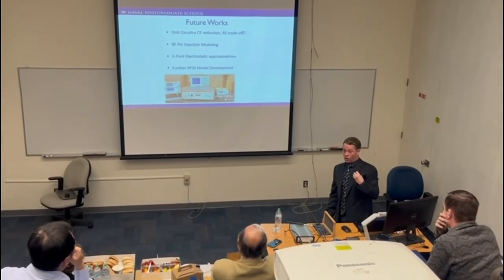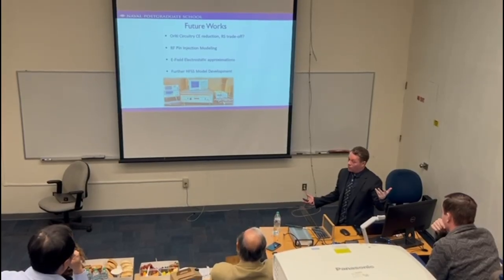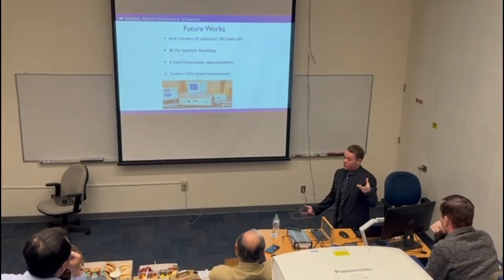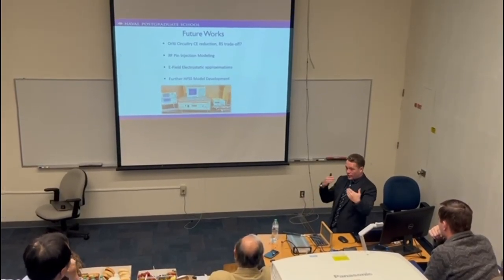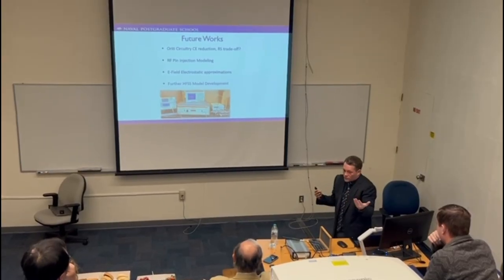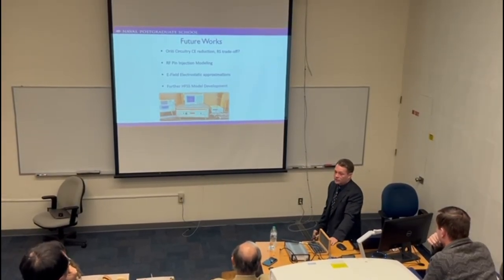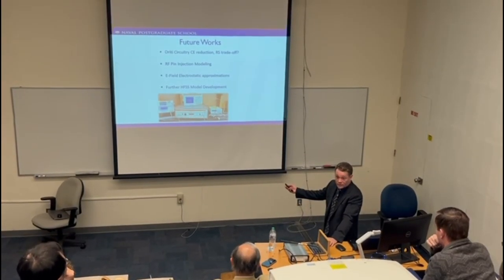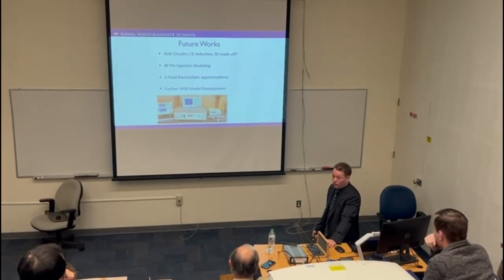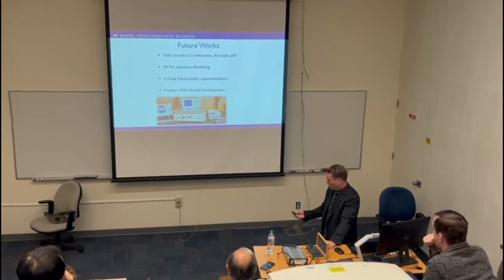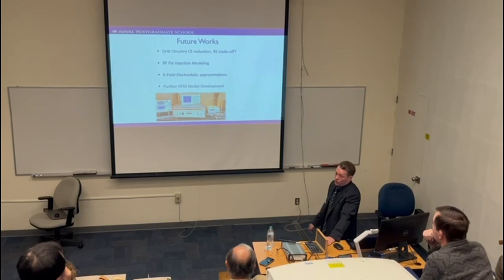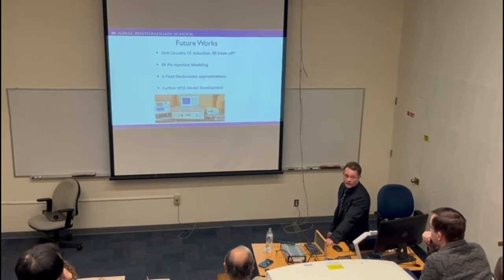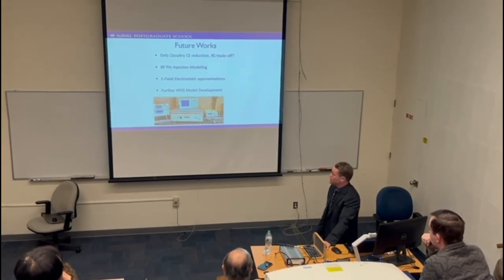So now I add more capacitance. Is that more common mode coupling? I add more inductance. Is that more differential mode coupling? Until you look at both sides of the coin, what's the trade-off? You could have improved conducted emissions, and hopefully it's a win-win: you improve conducted emissions and you improve conducted susceptibility and radiated susceptibility. But you don't know until you test it. I think it'd be a very fascinating master's thesis.